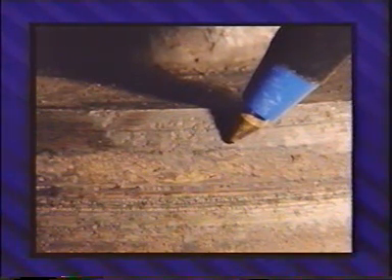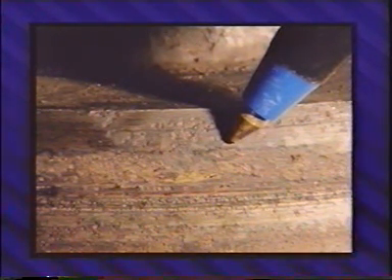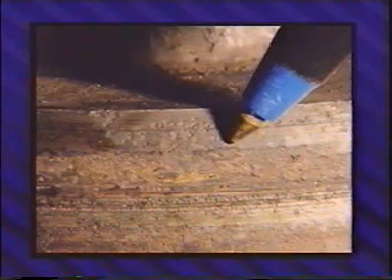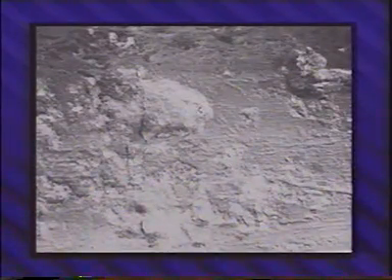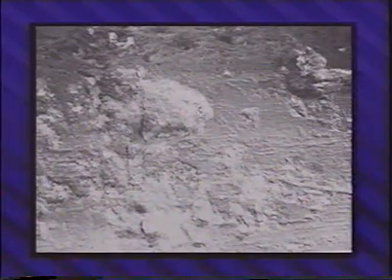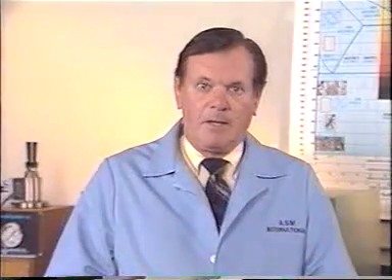Surface features of corrosion fatigue crack origins vary with the alloy and with the specific environmental conditions. In carbon steels, for instance, cracks often originate at hemispherical corrosion pits. Often these contain significant amounts of corrosion products. The cracks are predominantly transgranular and may exhibit a slight amount of branching. Except where they intersect the free surface, they resemble fatigue cracks that are not environmentally induced.